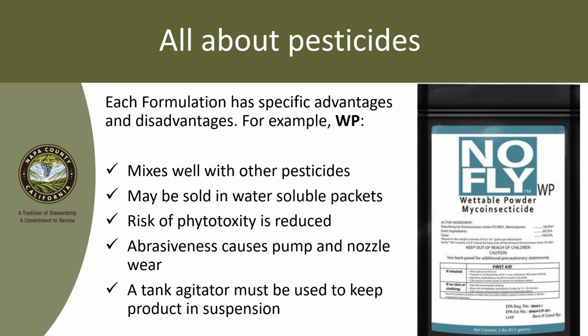But on the other side, with wettable powders, abrasiveness is an issue. That means that it can cause a lot of pump wear. It can cause nozzle clogging and wear. And the way you fix that is to use a tank agitator. So remember, with wettable powders, you've got to use that tank agitator in order to keep this product in suspension and stop it settling out inside the tank, where it's going to do some damage and lose its effectiveness.